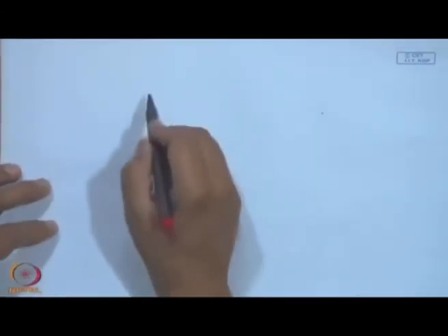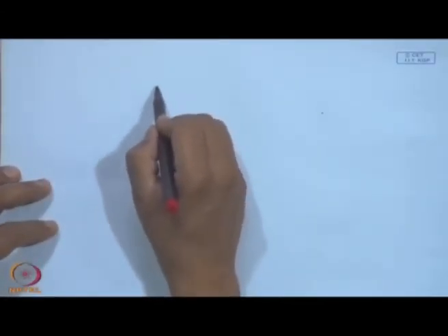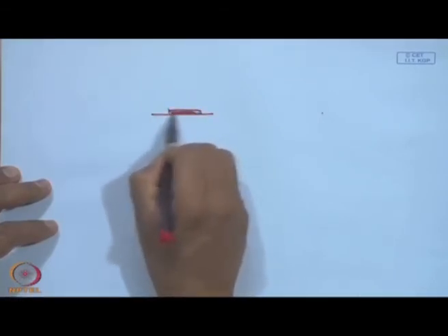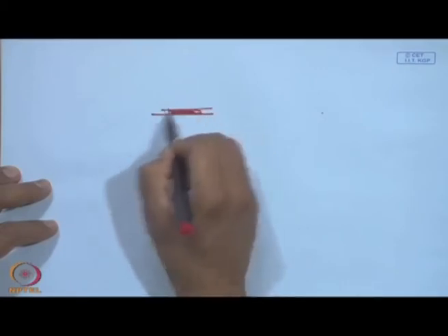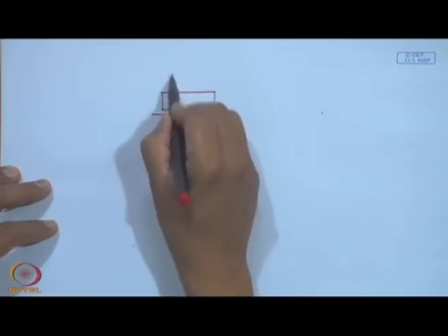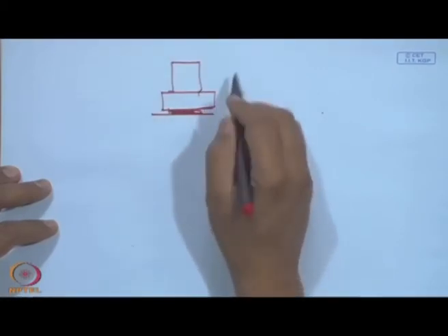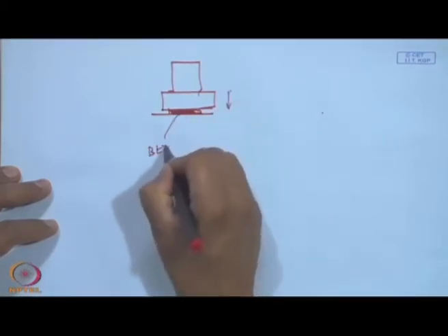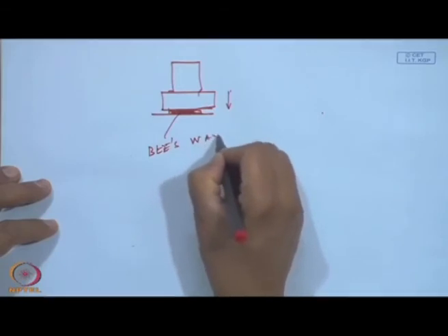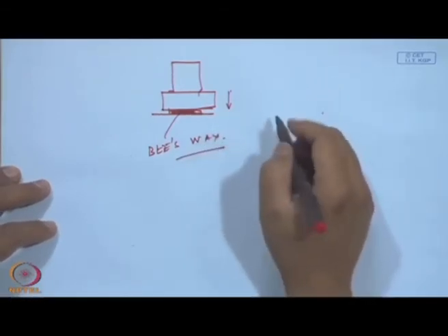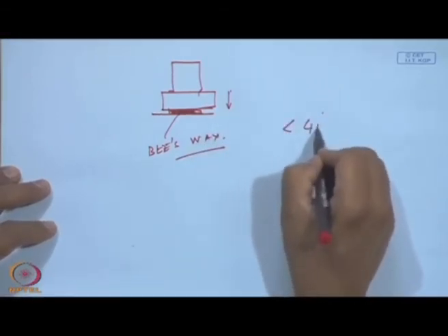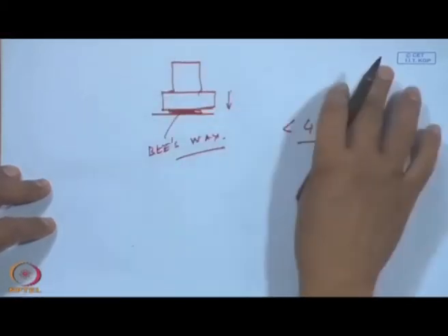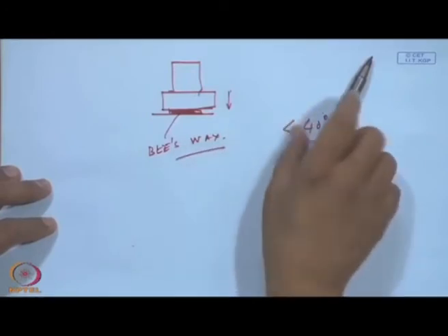But sometimes even just a layer of beeswax on a surface, the honey, beehive, beeswax, you can just put it here and then stick the accelerometer onto it. Okay. Just press it, and this is the beeswax. They are pretty strong. Okay. But the problem is you cannot use them beyond 40 degrees. In room temperature these are good, but beyond that they will melt.